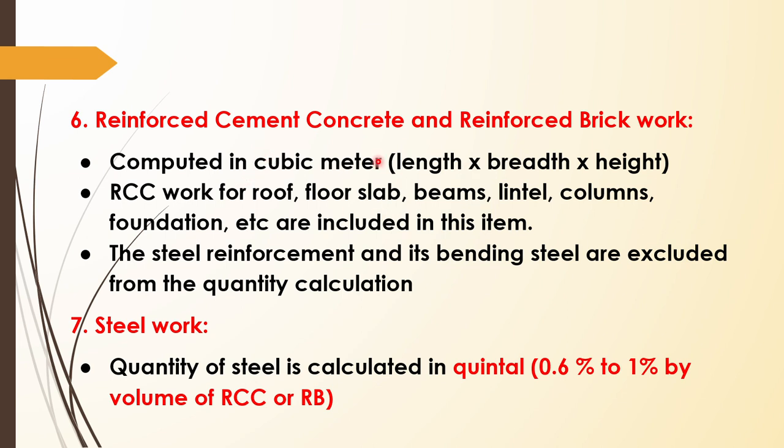Normally the quantities which we are taking in this case are floor slab, beam, lintel, column, foundation, etc., because in all those cases we are providing some steel elements in it. So steel reinforcement and its bending steel are excluded from the quantity calculation. For example, if you are making a pillar with reinforcement, then we will take the pillar as a single entity and calculate the RCC work for the pillar. Then we will subtract the amount of steel inside that. That is how we will find the quantity.